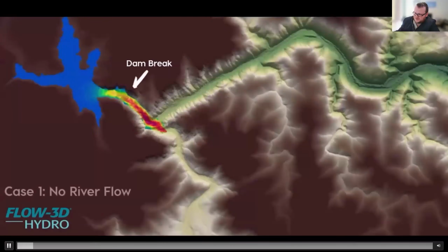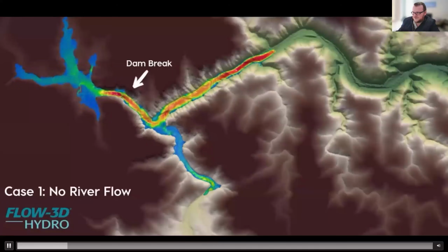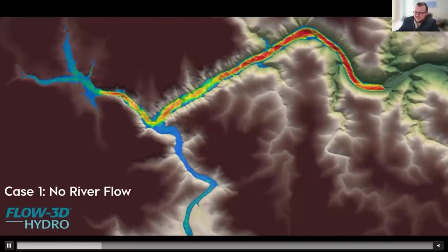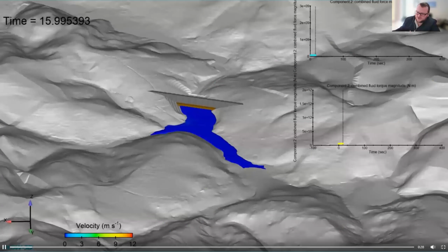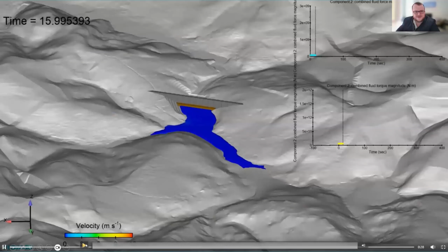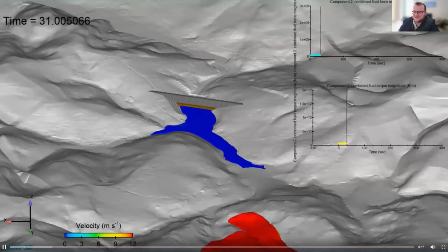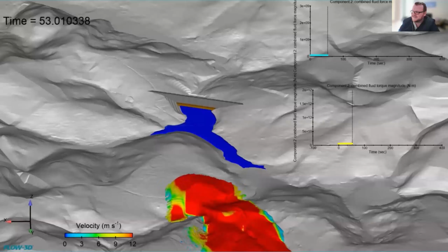And I shared a link to DualSPHysics. That's in FreeCAD, and it's a relatively easy SPH solver, a smoothed particle hydrodynamics solver for the Navier-Stokes equations, and it seems relatively user-friendly. But the trade-off is there's not a lot of documentation there either. So options exist out there, but it's all quite time-consuming, and you need to be committed to go down this path.